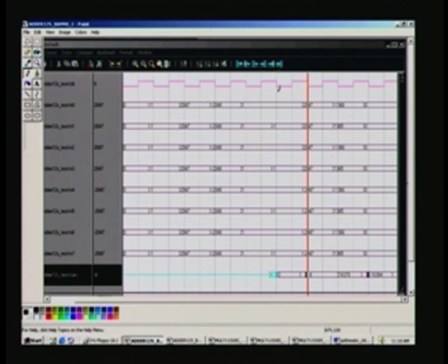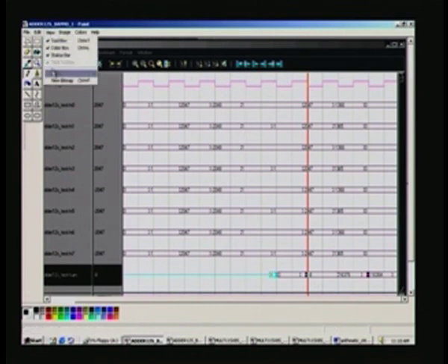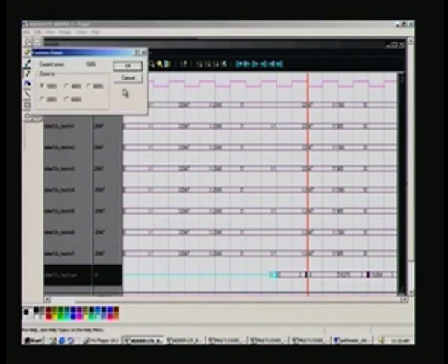So, after 5, after a further delay of almost some 5 nanoseconds or more, the result manifests here. This is because of back annotation. Actually, without back annotation you should have got it right at this edge. Because of back annotation, gate delays come into the picture, and the result arrives only after a delay, and clearly it is after the 5th clock pulse, and that is what we had designed for. We will zoom it here and see what the results are.